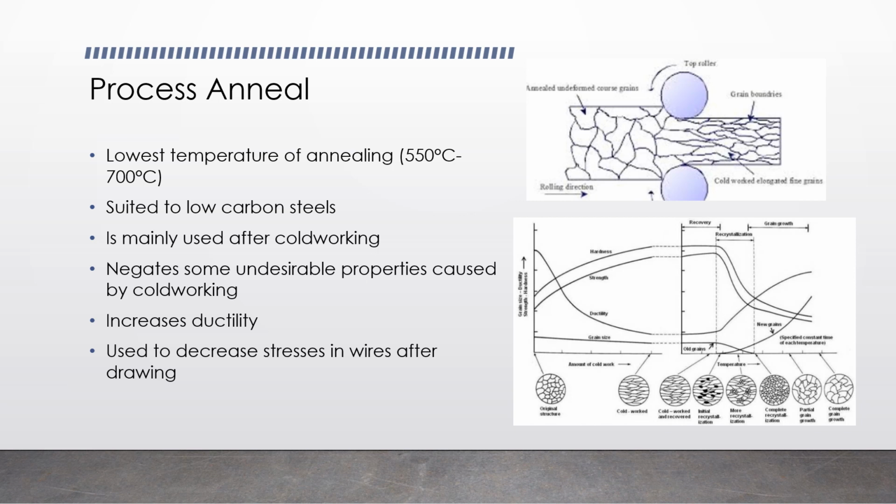On the top right, we can see a sample that is being cold worked. When a sample is cold worked, the grains become fine and elongated. These grains also have internal stresses. These factors cause the sample to be very hard, however very brittle.